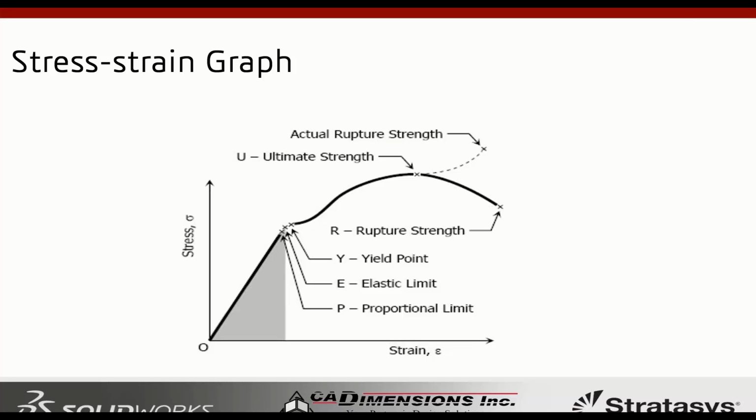In addition to that, it will not linearize your results, and if you have any external loads, it will keep the external load normal to the face as opposed to normal to a global coordinate system, which is not very realistic, as you will see in my example here today.